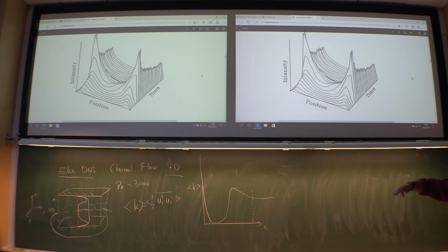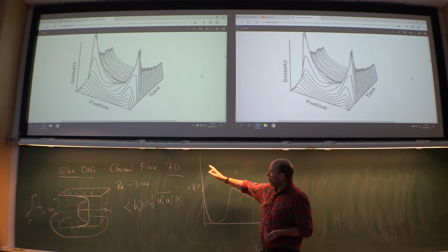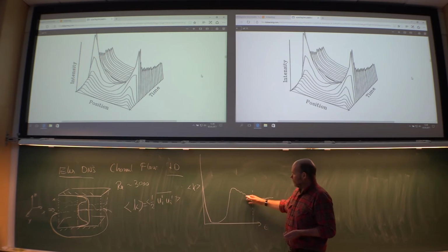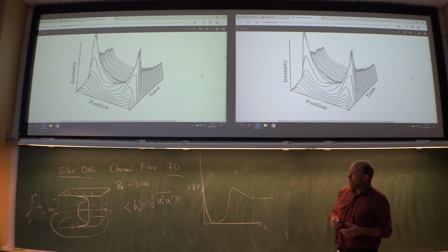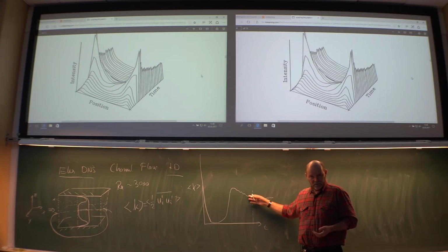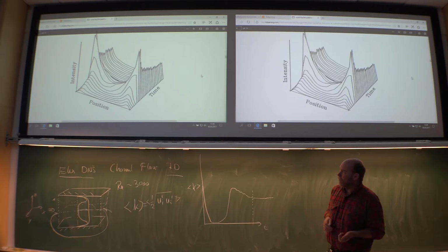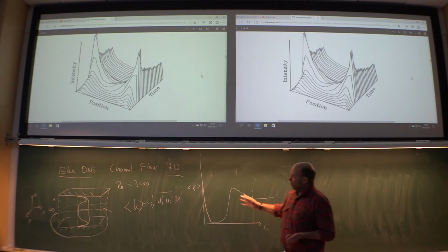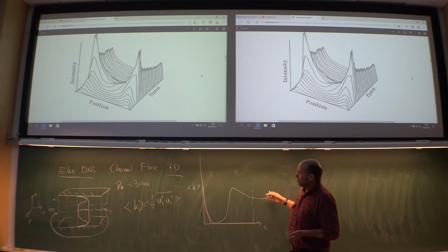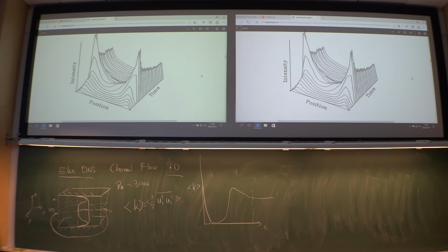So here, with respect to time, initially you have something totally unphysical, but then through the Navier-Stokes, he sort of organizes himself, establishes a correct turbulent field, and then somewhere along the line you start saying that, okay, now this is a good representation of the real physics. Start with something totally rubbish, and then sooner or later, hopefully, you will obtain correct